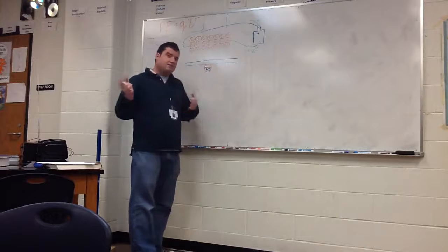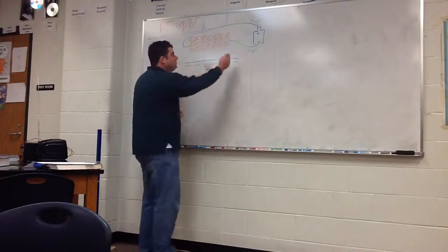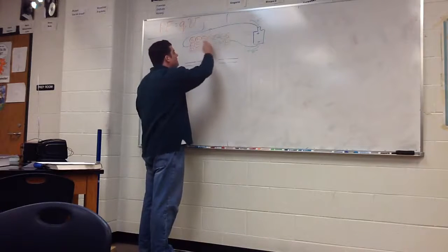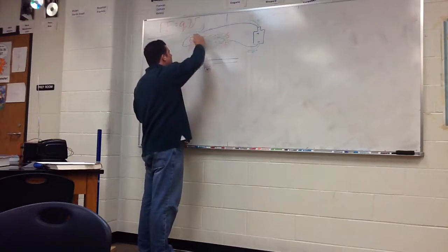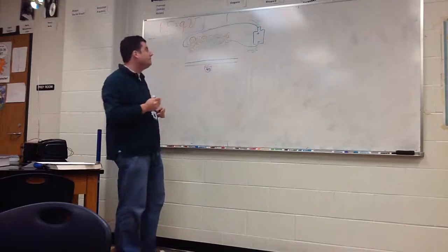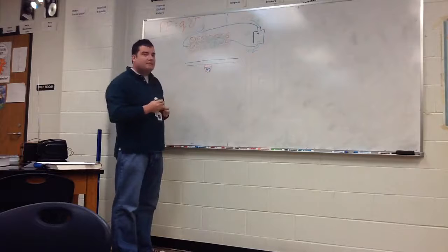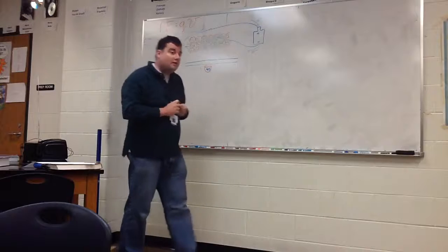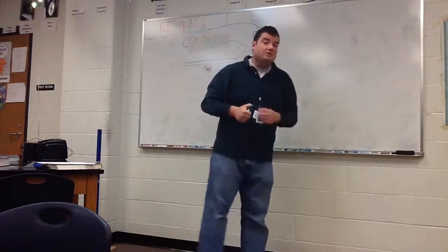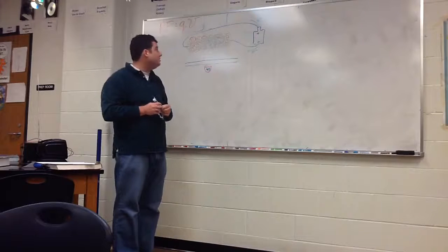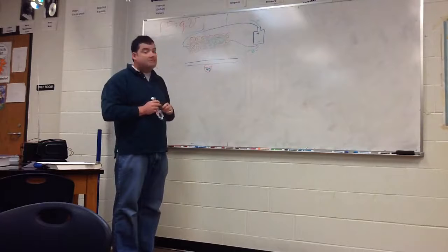We'd like to say that that's like a river. They go in just one direction. But it's not really true. What's actually happening is they are going all around. And there's a very small drift speed that means over time, they actually do make it from one side to the other. But all of this moving around, it knocks the copper atoms around, it gives them kinetic energy. And the kinetic energy of atoms is actually what temperature is. So what's happening here is this wire is converting some of the electrical energy that I wanted to go through it. It's converting it to heat.